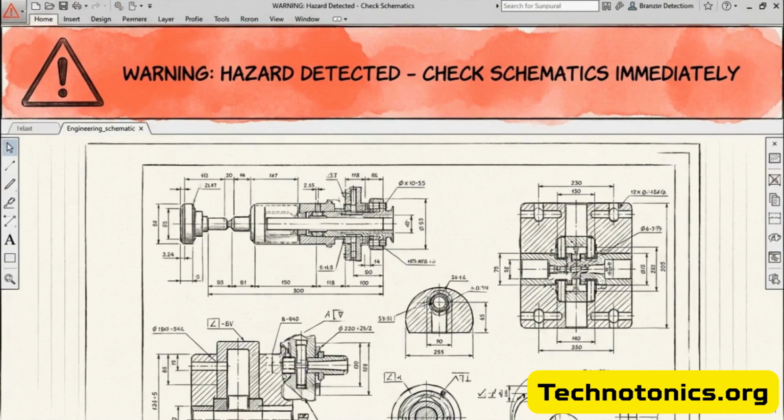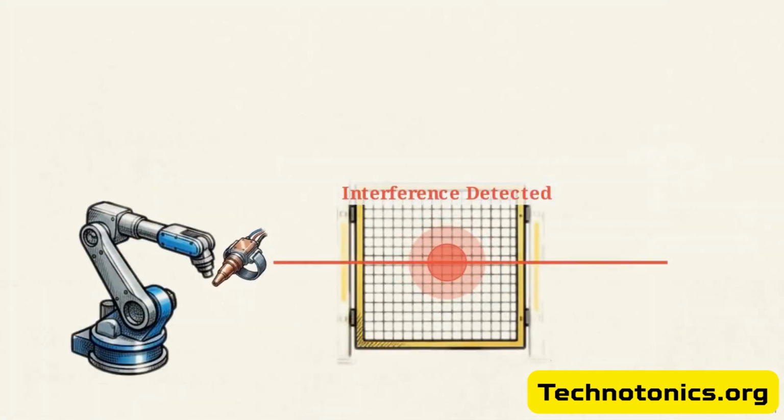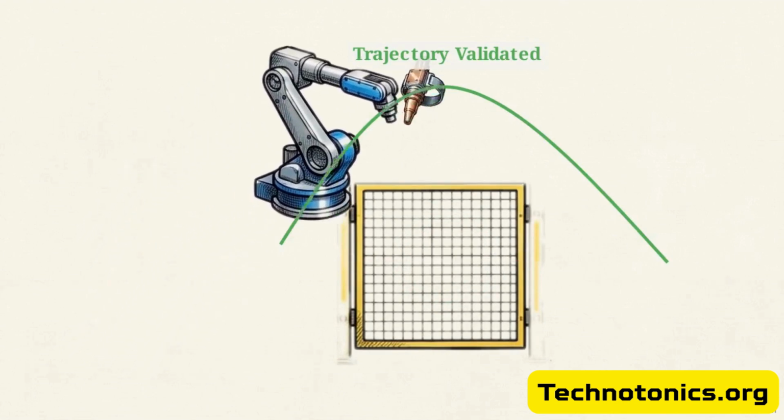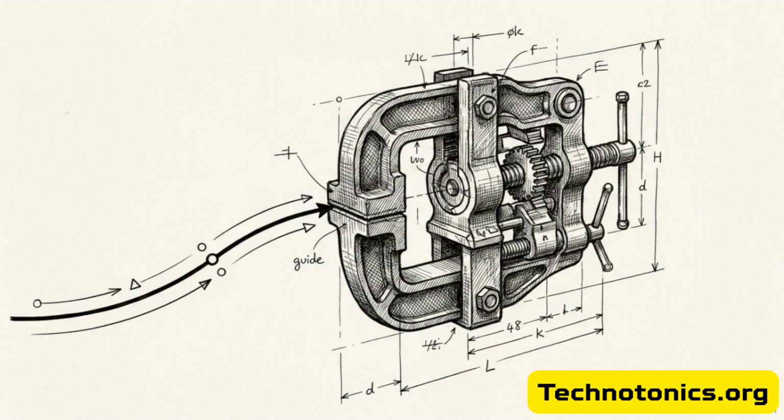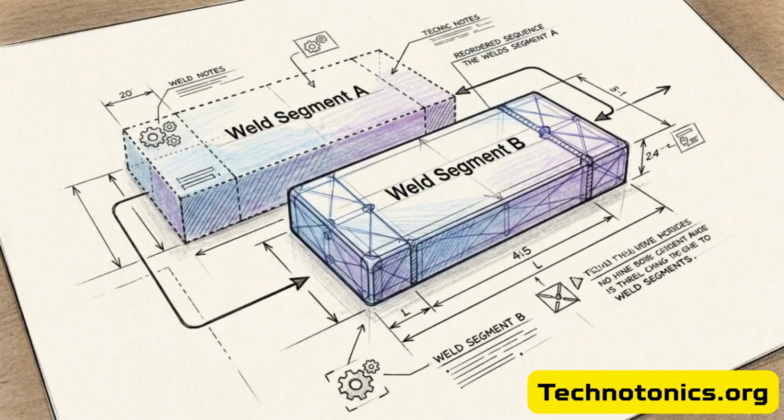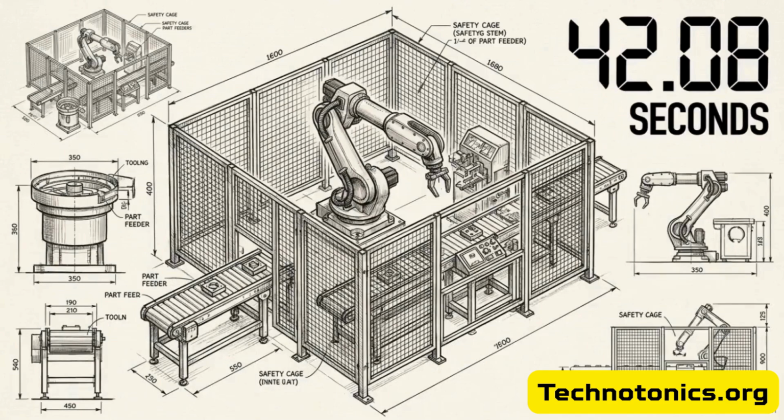If an approach is completely blocked by a clamp or fixture, entire machining operations can be quickly reordered in the virtual space to bypass the clearance issue entirely. With a safe path confirmed, we execute the full sequence to simulate cycle time, providing a highly accurate measurement of the system's true mechanical throughput. This allows teams to measure takt compliance without touching a stopwatch. The simulation isolates exactly which motion segments are creating operational bottlenecks.